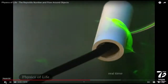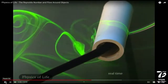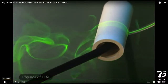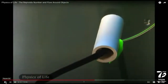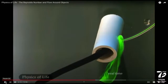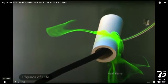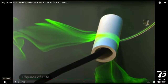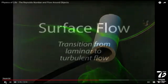If we drop the flow rate very low, we can bring Reynolds numbers down into the hundreds. There are still vortices being generated, but they now have an obviously laminar component to them. This means that viscous forces holding the flow together are now similar in magnitude to the inertial forces that initiate turbulence. It's even possible, with a few tricks with the flume, to drive Reynolds numbers for the small cylinder down into the tens and single digits. There is still a very slight rotational component to the flow, but the flow is definitively laminar, held together strongly by viscosity.